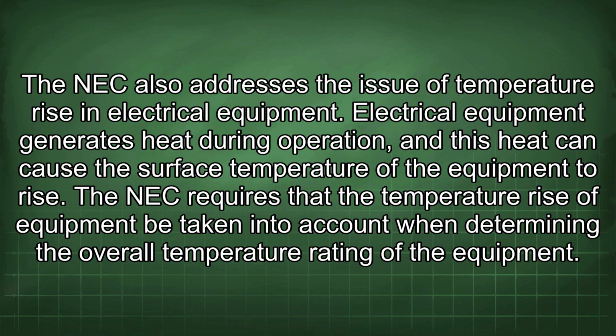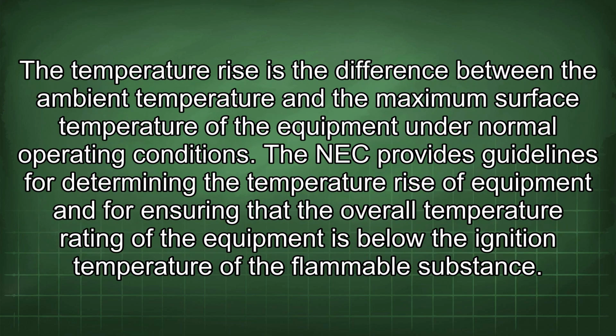The NEC requires that the temperature rise of equipment be taken into account when determining the overall temperature rating of the equipment. The temperature rise is the difference between the ambient temperature and the maximum surface temperature of the equipment under normal operating conditions. The NEC provides guidelines for determining the temperature rise of equipment and for ensuring that the overall temperature rating of the equipment is below the ignition temperature of the flammable substance.